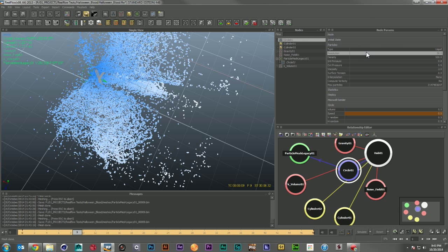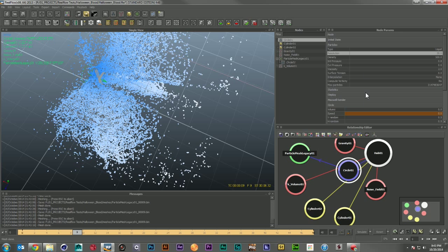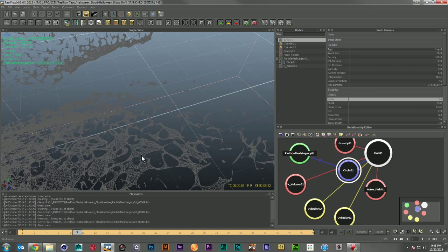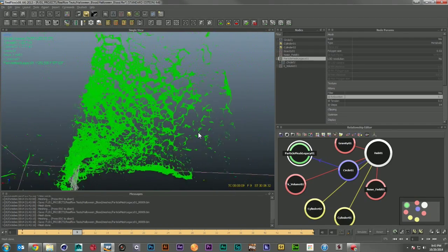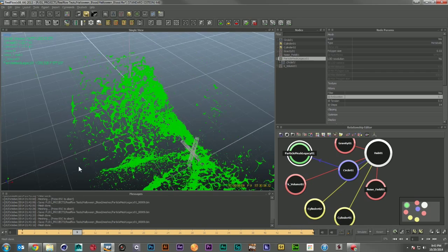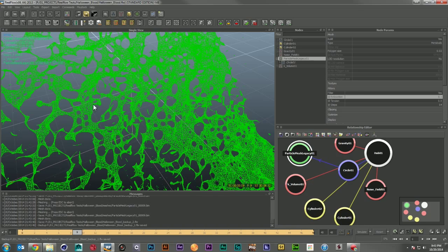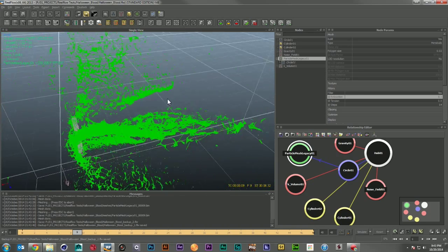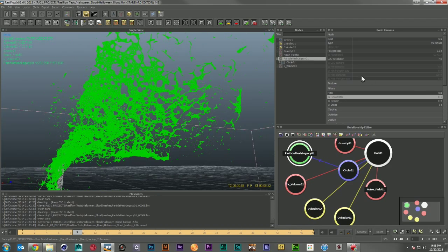So I'm going to take my particles and go to the display and just turn them off for a moment. And you can see we have these weird spider's web meshy kind of things happening. And that is what happens when you have way too much relaxation. You just get this really kind of crazy pattern. And that can be good for things, but this does not look like liquid. And it's usually the sign that somebody had way too much relaxation going with their simulation and build.